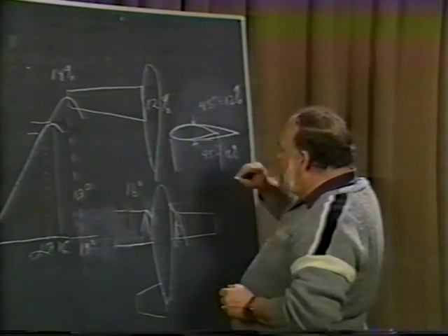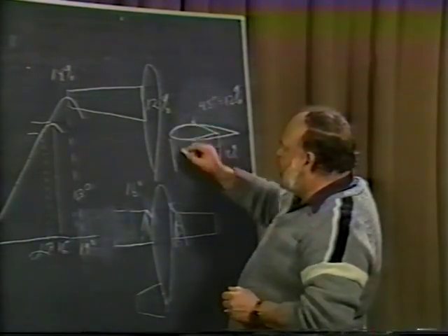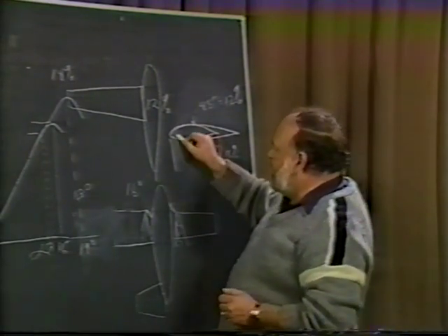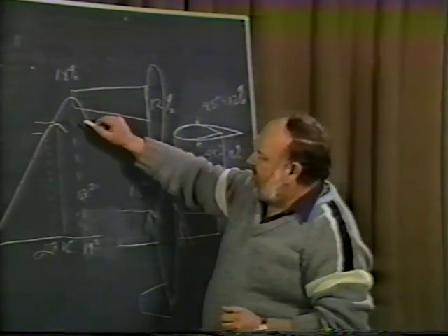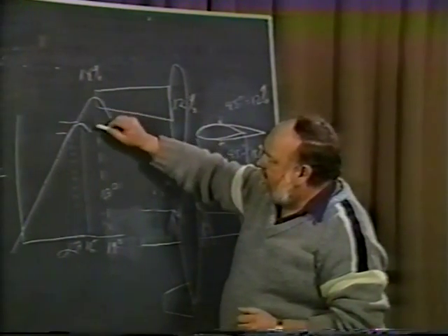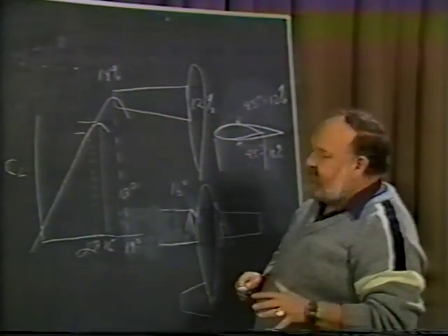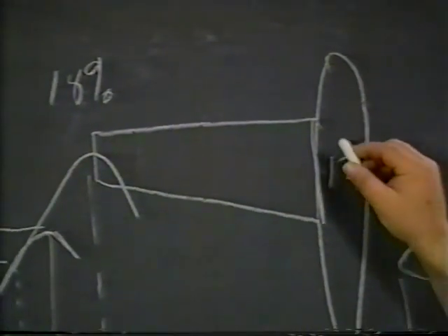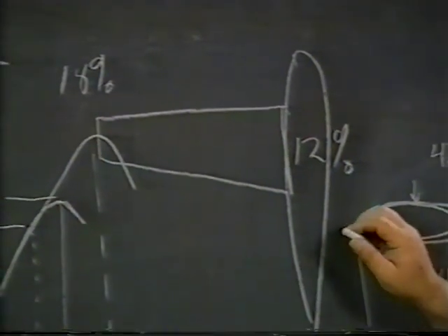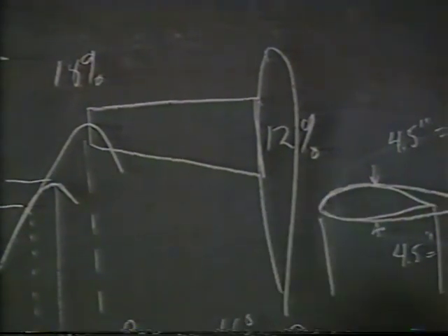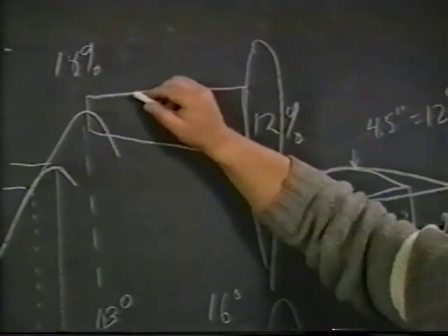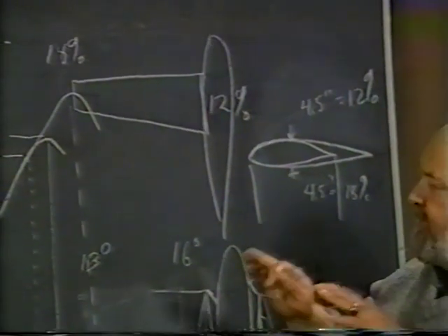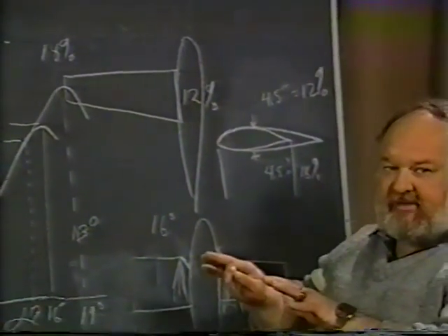That has its advantages. But being a relatively thicker percentage airfoil section with a relatively larger leading edge radius, we ended up with a real nice lift coefficient. Our lift coefficient went higher at the tip, and it was 3 degrees later than what the inboard section would stall. What does this mean? Well, it means that not only do we have this tapered wing section, and this excellent stall pattern, because the outboard section is going to stall 3 degrees later than the inboard section, it means that the pilot can pull the airplane up, get into a stall, have it sit there and buffet.